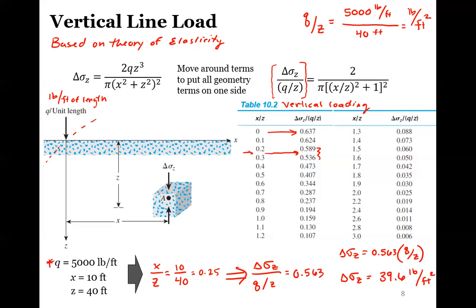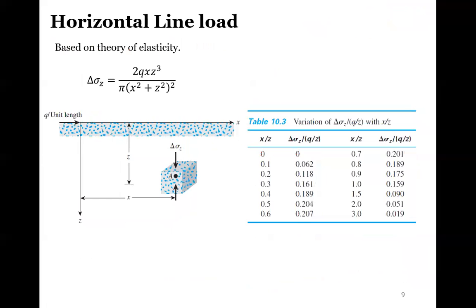So this is a vertical line load. These are used sometimes in fence lines or walls. But point loads often aren't analyzed because it's always going to be a cross-sectional area that we're applying any type of foundation through. But if we can do vertical line loads, then we can also do horizontal line loads. This is really beneficial because we always will be designing something to withstand the weight or this vertical loading, but especially in Florida, we have wind, we have waves crashing on walls, we have horizontal and lateral loading as well that we need to consider.